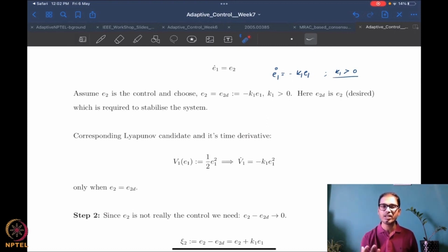We take a derivative and we choose a parameter update law so that we ensure that V dot is negative semi-definite. So this is called Lyapunov redesign, right? And that's what we are used to doing. Okay, so we are not covering the notions of control Lyapunov functions in this course, but essentially what we're doing is choosing a control Lyapunov function and getting a corresponding feedback u, or in this case theta hat, which is making V dot negative semi-definite at least. Okay.